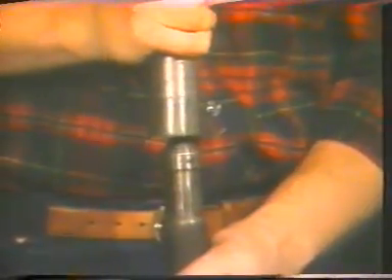In some cases, the wireline specialist may choose to drop a go-devil before the cutter bar. The go-devil is used to provide a base for the cutter bar to mash the wire against. The go-devil is slotted its entire length and is designed to be pinned to the wire line. After dropping the go-devil, a cutter bar may then be dropped to cut the wire line at the top of the go-devil, after which the go-devil can be retrieved.